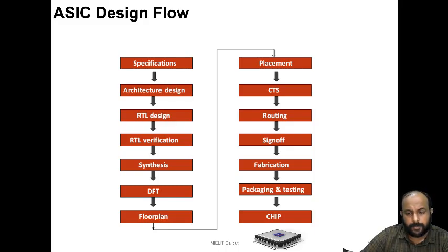They are responsible for building an appropriate architecture of the design. We might be familiar with the architecture of many processors, DSPs, and so on. Basically, an architecture is a representative view of how the design should look, whether it be an ASIC or a system on chip. This architecture will be broken down into different logical portions.